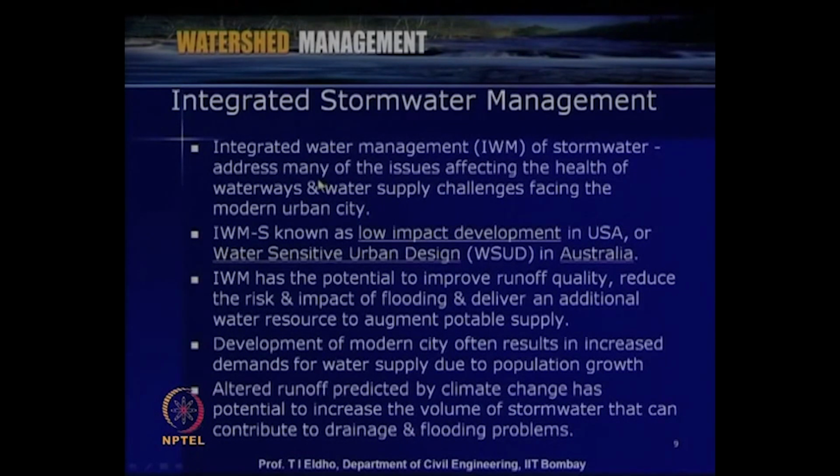So, when we effectively utilize the water at the local level wherever the stormwater occurs, we are reducing the water related problems, since we will be recharging the water or storing it at the local level, and that can be directly utilized. So, integrated water management of stormwater is known as low impact development, LID, in the USA, or water sensitive urban design, WSUD, in Australia.